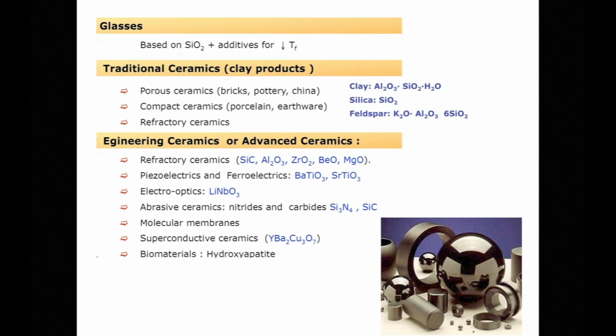And then what we call advanced ceramics or engineering ceramics will indicate that they need to be cured, crystallized, and processed very specifically for high-end performance, whether it's refractory application or piezoelectric, ferroelectric, barium or strontium titanate, lithium niobate for electro-optics, nonlinear optics, abrasive ceramics like silicon nitride, silicon carbide, molecular membranes, or even superconductivity materials such as yttrium barium copper oxide, various types of biomaterials or bioglasses, or even biocompatible surfaces made up of hydroxyapatite, very useful for bone growth, like calcium hydroxyapatite materials.